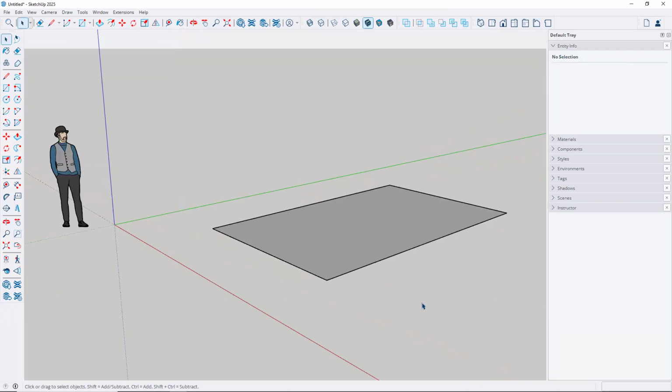So what you have here in SketchUp is a surface. And if I give it one click, you see how it highlights the surface. And this surface was made possible by constructing 4 edges, but I could have gotten away with it by constructing just 3 edges. So it creates this plane. So I'm going to click off of that so it's not highlighted. So to model in SketchUp, you need to start with the surface and then you have to push-pull it.